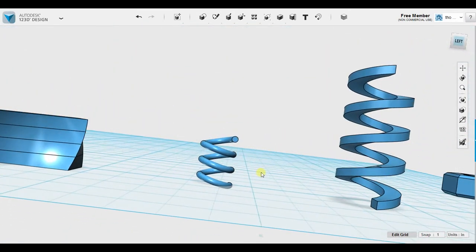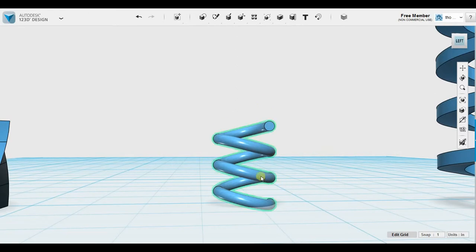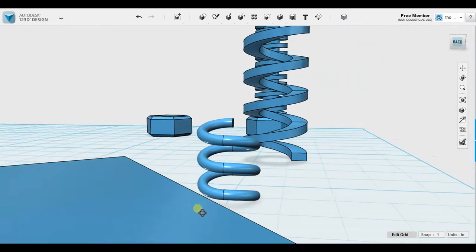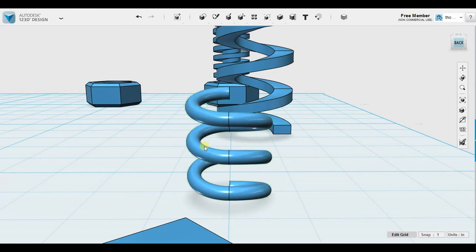Next one was making it with the torus and cutting it in half, rotating each half and connecting the faces to make a helix. Well, right here on this face it looks great. It's all angled properly and looks good. But when you turn over here and look at it, it straightens out right here. So you're going from a curved or angled line to a straight line, back to a diagonal line to straight. That's not a helix. So that didn't do me any good.